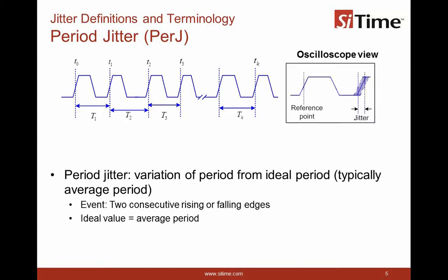In the old times, the way it was measured was to basically trigger at one edge and look at the deviation or movements of the second edge relative to the first edge. That was a very intuitive way of looking at jitter, not necessarily the best way to measure jitter. Today with digital oscilloscopes, this is hardly used. We also don't recommend using that method.